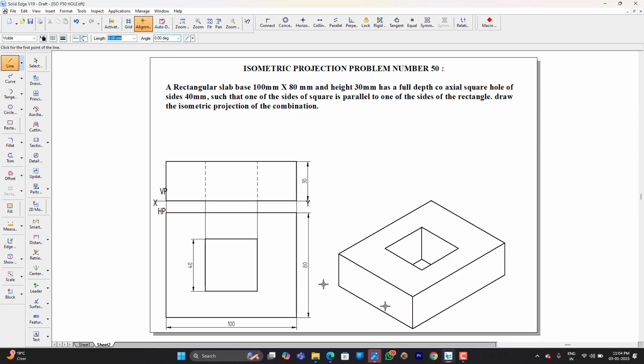So what are the dimensions that I have to show? I can just draw two horizontal lines on either side and I can show it is inclined at an angle of 30°. So use angle between, select this and select this, show 30°, select this and select this, show 30°. I think that is more than enough. So this completes the problem.